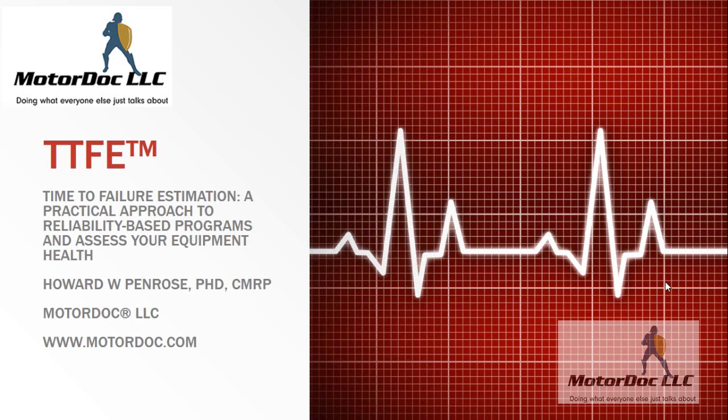Welcome to this presentation on time to failure estimation brought to you by MotorDoc LLC. In this presentation, we'll discuss the importance of proper PDM technology selection and how the frequency of testing can be applied. We'll also discuss how to use the P to F curve to put your program together and how you can provide risk of failure assessments associated with the application of predictive maintenance.